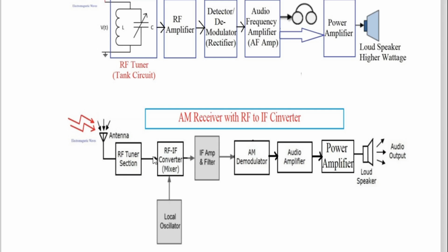And that is why this circuit is very important. But to do this job, the circuit becomes complicated. Why? Because your selection is of one particular frequency only, and you want to reject all others. Therefore, to convert the radio frequency into the corresponding IF, the job becomes complicated, and therefore you will require one local oscillator.